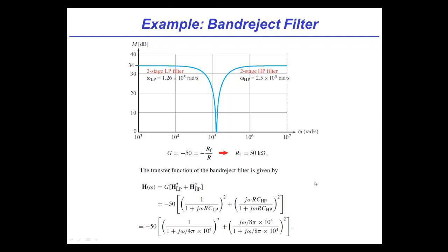Yeah. So these active filters are pretty nice because you can break things up into individual parts and design each part carefully, and so you can build more sophisticated elements this way. They work great. Remember, one of the things we glossed over, and if you take more advanced classes, you learn about this: in all this analysis, we assume the op-amps themselves have no frequency dependence. In other words, they're essentially perfect. And that is one of the complications in real active filter design: the op amps themselves are not perfect. That's right, because they're made of transistors, and those transistors have associated capacitances, and they contribute poles and zeros to the behavior.